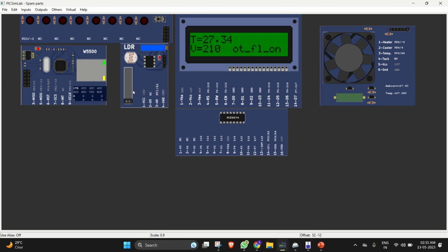So the LDR will read the sensor value. Based on the reading from the LDR, it will vary the brightness of the LED, which resembles controlling garden lights based on the availability of sunlight. We have to connect the Arduino Uno with the LDR sensor and the LED lights. So this is the first requirement of our system, and it is known as garden light control.